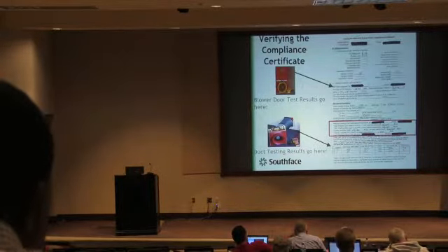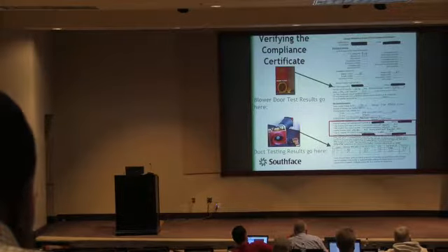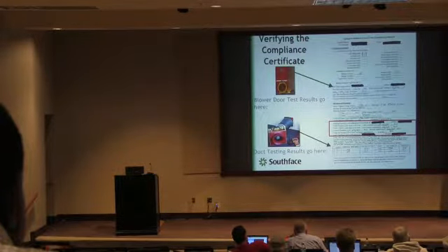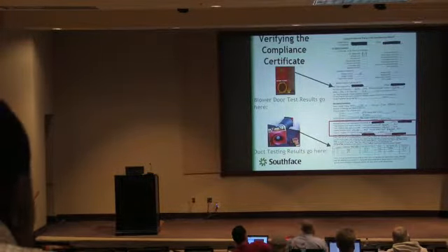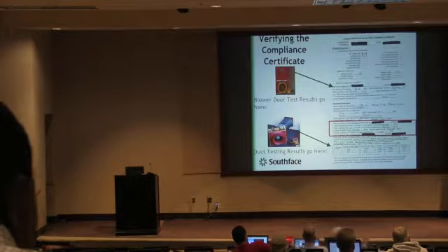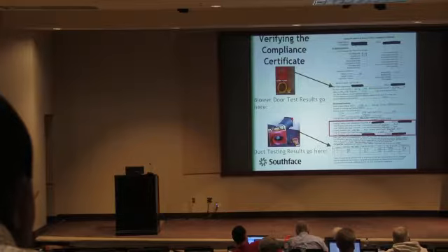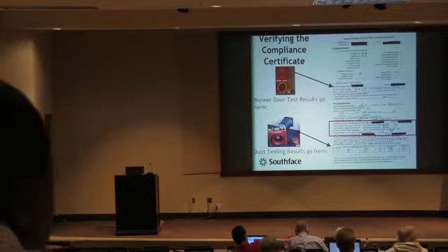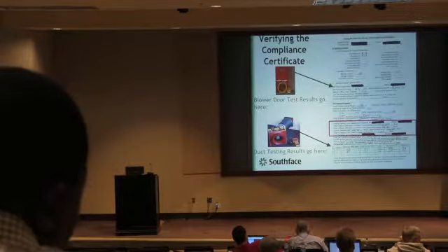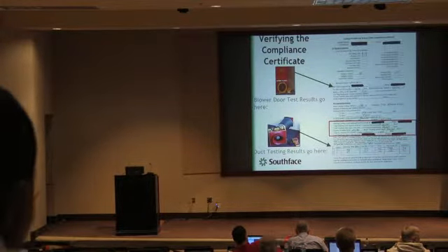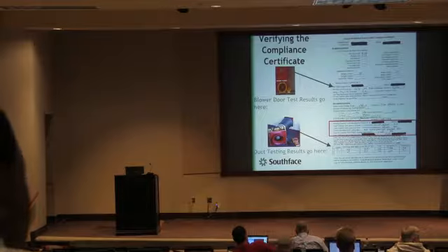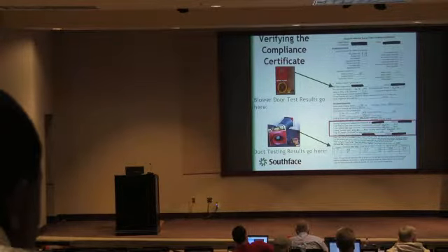High performance windows are a big factor, which means the rules of thumb from 20, 25 years ago are not applicable to new homes constructed today. But the problem is builders are still buying by the ton. So the heat and air contractor puts in something too large, because that 3-ton system only costs $7 more than the ton and a half system, but he gets $2,000 more. We really ought to not pay by the ton. It doesn't make any sense, and that's what we were talking about.